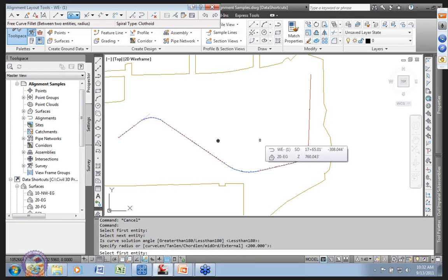up together. So the better you understand the tools available to you in each one of these interfaces, and how you can modify things and how the commands relate to one another, a simple rule of thumb: if it's not in the layout toolbar, you're probably dealing with AutoCAD line-based tools. So these things in the draw menu create the AutoCAD line work first, and they're LDT-like in that sense. And then you can modify those, make them into alignments and modify those. So that's a good way to do it.